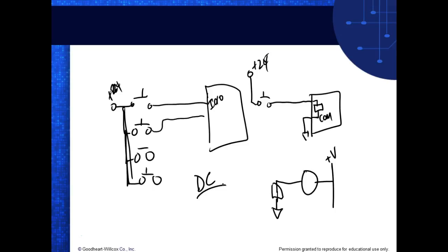If you were working at US Steel and you were working with the 1100 PLCs, that's 120 volts. Then you would probably be required to wear safety glasses. When you make measurements, anything over 240 volts, you're supposed to use insulated gloves, or at least leather palm gloves. We're going to have to change the motor controls around a little bit to require that.